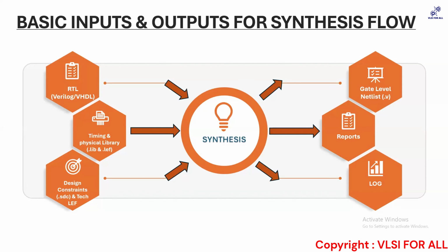So these are PNR constraints, whether I should use certain cells or not. There are different kinds of CTS level constraints as well that you have to provide. Kindly use this kind of cell list, don't use this kind. Whenever you are building a clock, you're allowed to use only clock buffers or clock inverters because they have an advantage over normal buffers, but the disadvantage is that their size is bigger. But you want your timing to be met and a good clock driving capacity. So constraints are nothing but guiding your tool on how to produce a design meeting your specifications, nothing else.